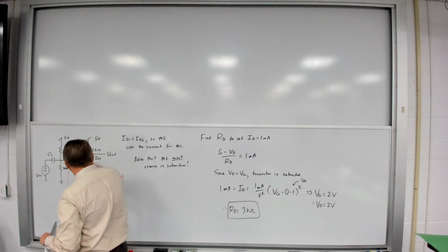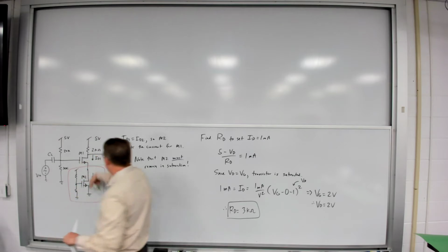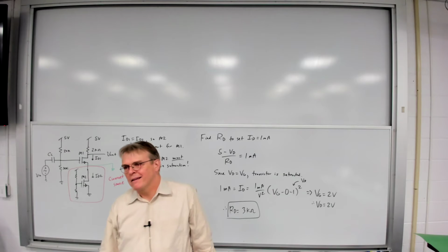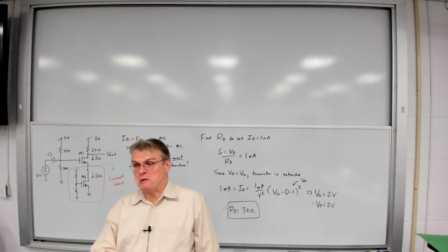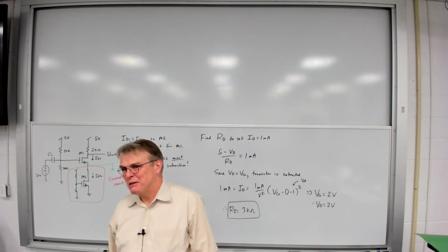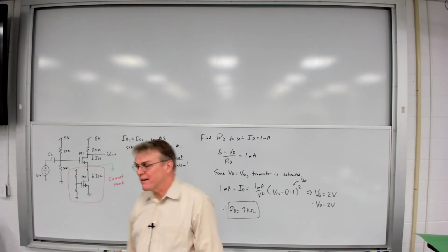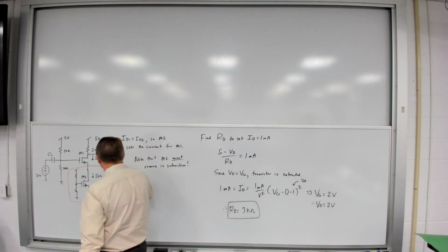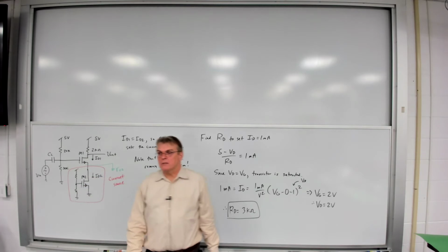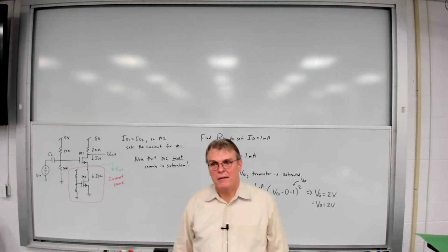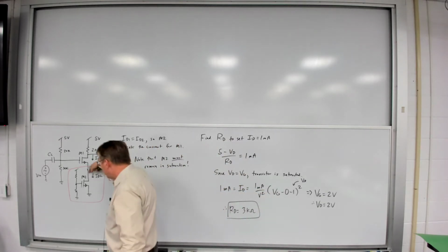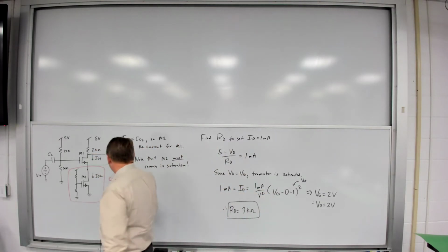This is a current source. What is the resistance seen looking down into the drain of M2? Is that going to be small or is it going to be large? That's acting like a current source. So what's it going to be? It's going to be big, okay? In fact, what you're going to see here is little r sub O2. You can do the small signal diagram yourself and check that. The resistance seen looking into the drain is simply going to be set by the r sub O, which is going to be big.